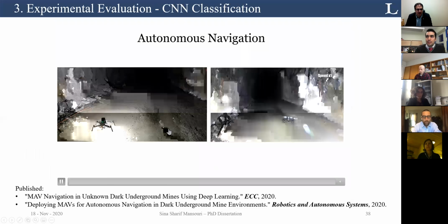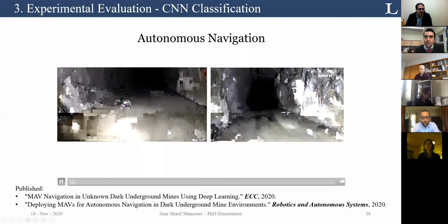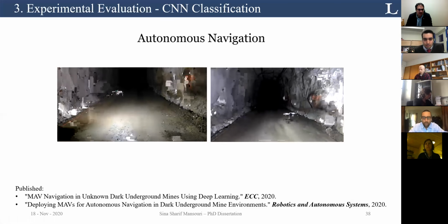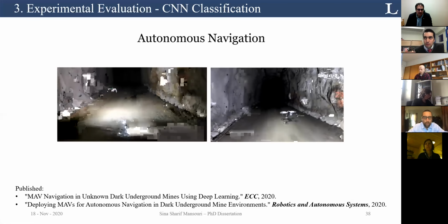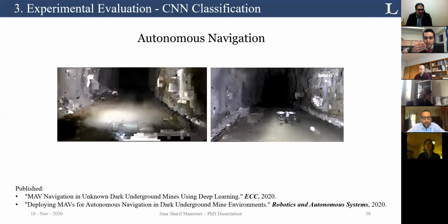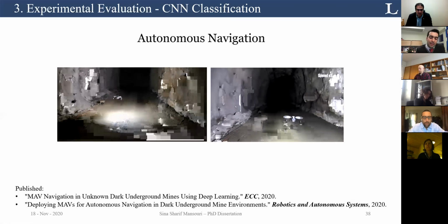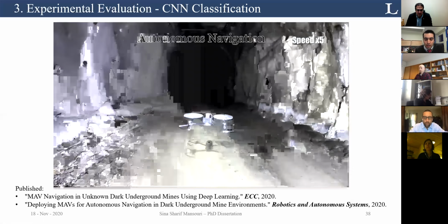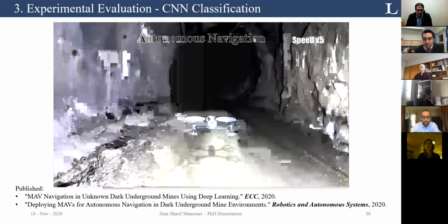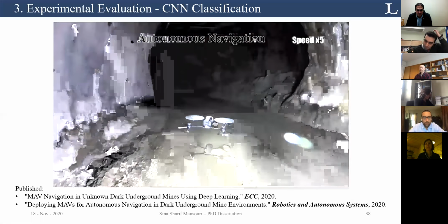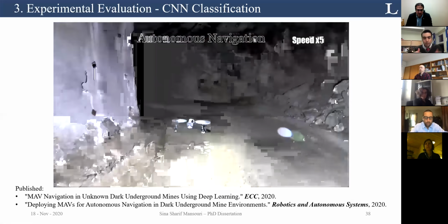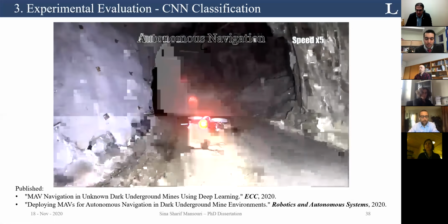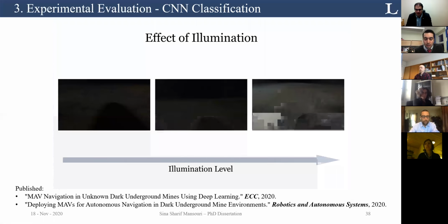Here you can see the test flight that we did. We noticed that we are having a bit more heading oscillation, or let's say higher frequency of control action, and this is mainly due to this binary classification, because a bit of rotation gives you the other direction of the wall and results in a different direction of the heading commands.